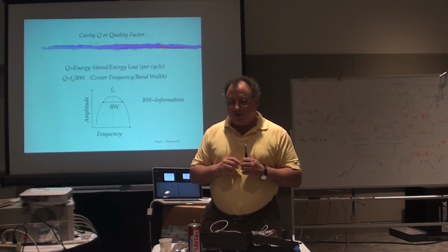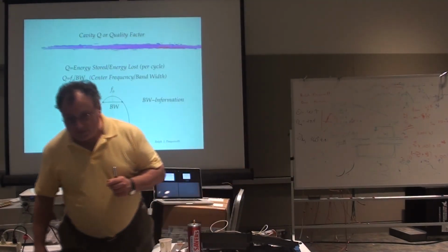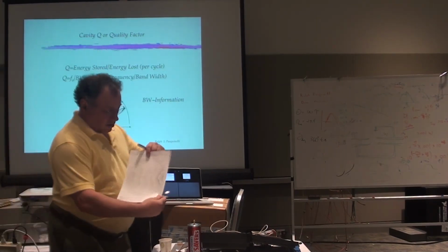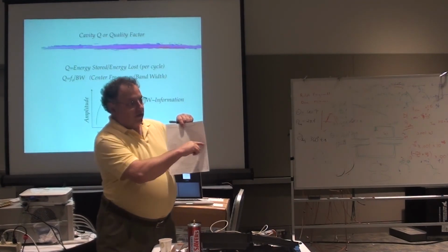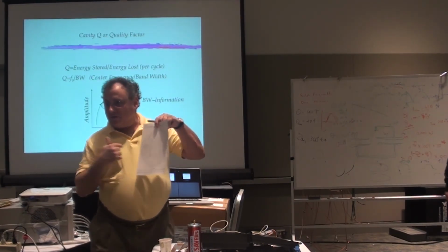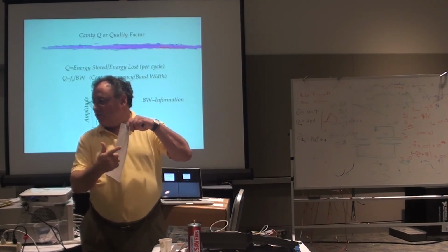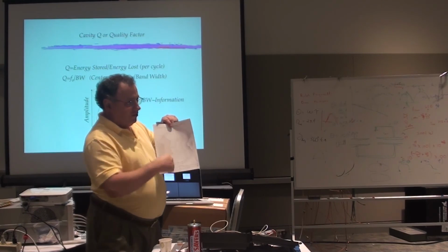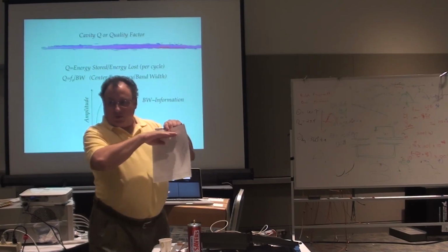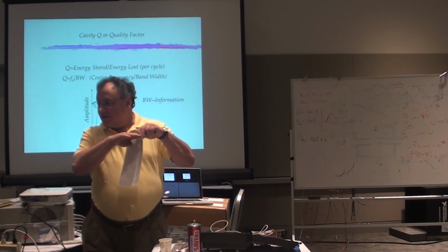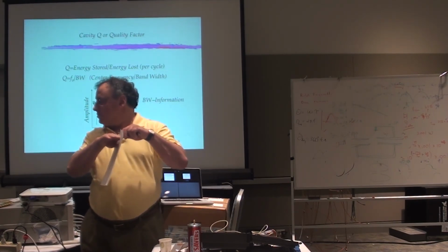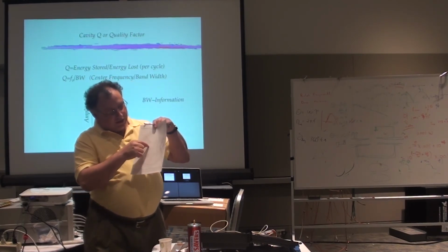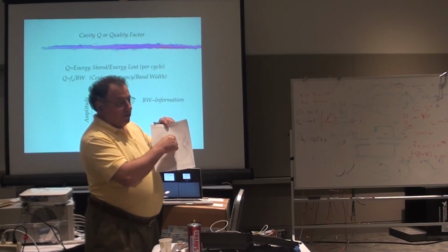And what happens there is when you have a Smith chart, and that's another beautiful thing about the Smith chart, is how intuitive it is: very low Q is right along the real axis. But remember, if I traverse the real axis, then of course I'm going to lose power because I've got resistivity. And you saw as we were doing matching networks, we were going to the unit circle hither and thither. But the further away I get from the real axis, the Q gets higher. And so Q getting higher means less bandwidth. And so a really broadband network will maybe do a lot of zigzags around the real axis,